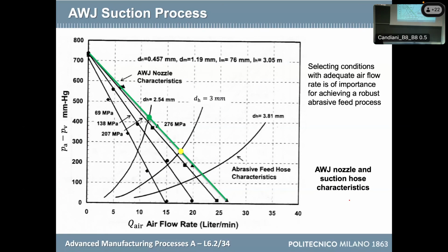But I shouldn't exaggerate, because otherwise, what happens here is that the velocity of the air wouldn't be enough for pushing the grains of abrasive. There is a limit. So these studies arrive at the best configuration. Also experimentally, I can try all of them. I will work in different positions, and then I could select in the design phase. This is not something that the user usually does, but this is for the manufacturer of the cutting head.